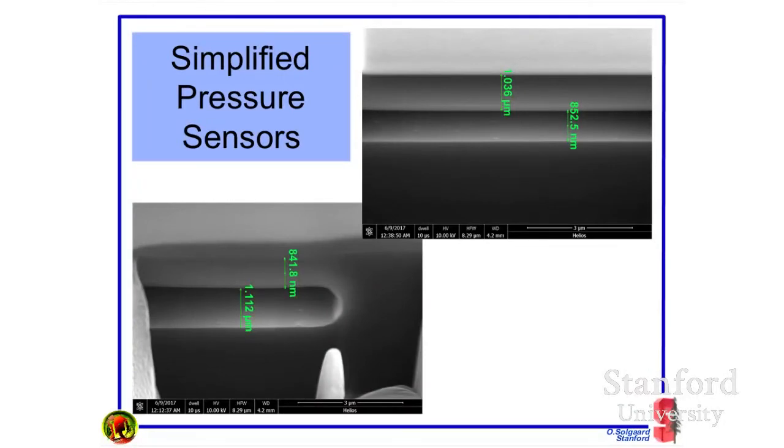And simplification is super important here, I believe. We really need to have things that are simple if you're going to go to the Internet of Things. So that's why I love this particular pressure sensor. It's just silicon, and it has just a void in it. And I can read it out capacitively, like we talked about before, how much that upper diaphragm has displaced, or I can measure it optically. There are a number of different things I can do with that, but it's super simple.